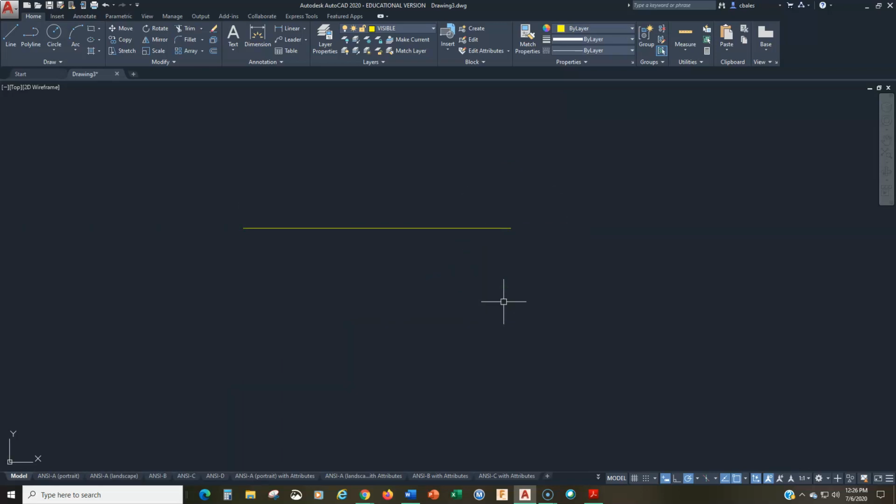Now, technically speaking, AutoCAD doesn't know millimeters from inches. It deals in units, so this was 7 units long that I just drew. But there are different scaling factors that help us to draw in millimeters or inches, and this was in the proportion of an inch drawing.